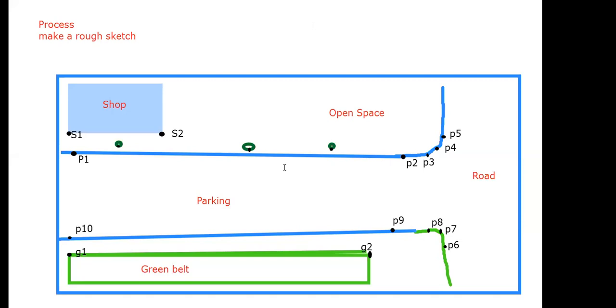So after selecting that, we will mark the position of the chain. So this is the area where we will mark the chain. Now the rough sketch is complete. Now you will go out into the field. First thing you have to do is to extend the chain.